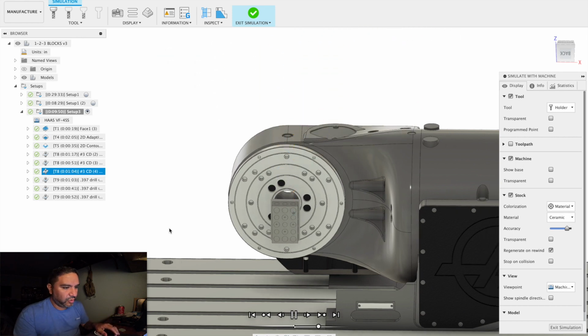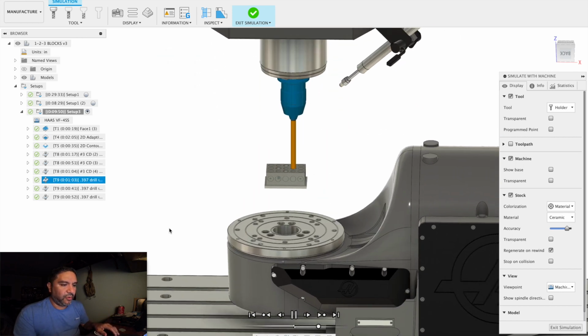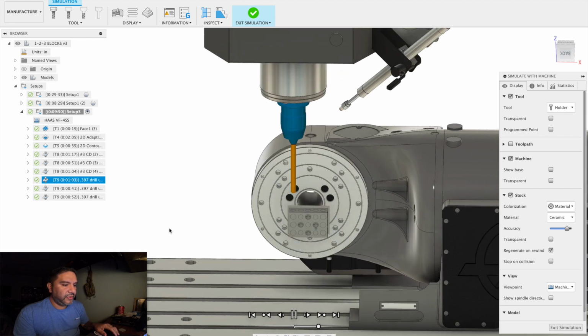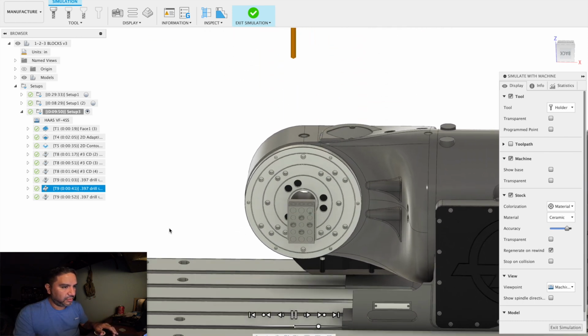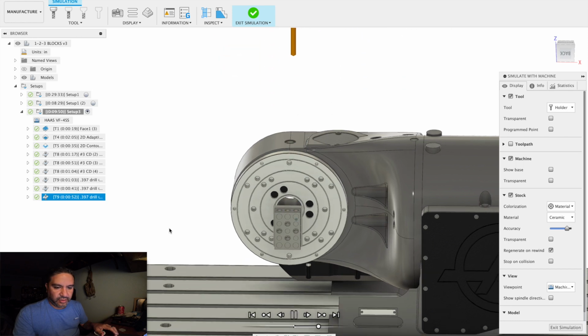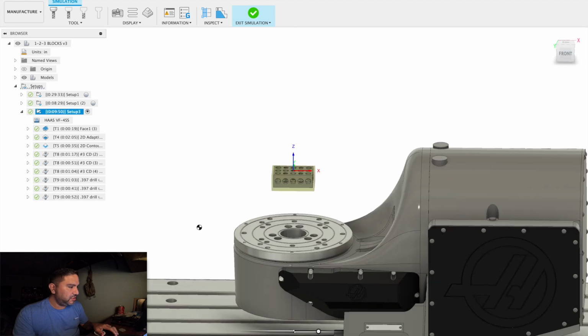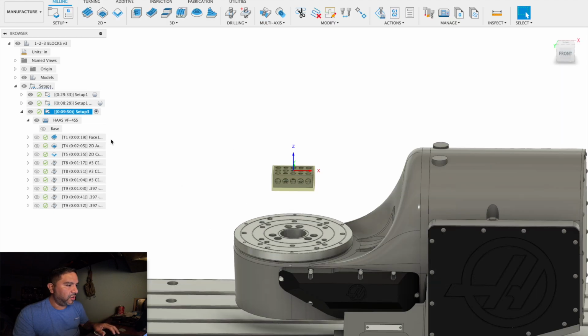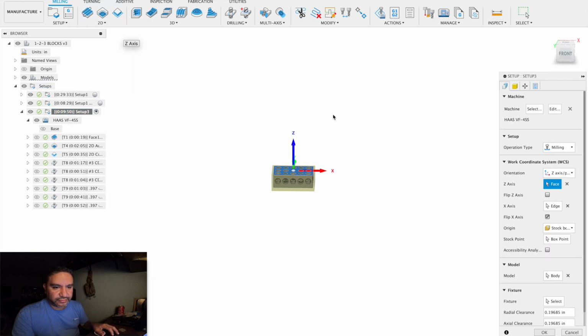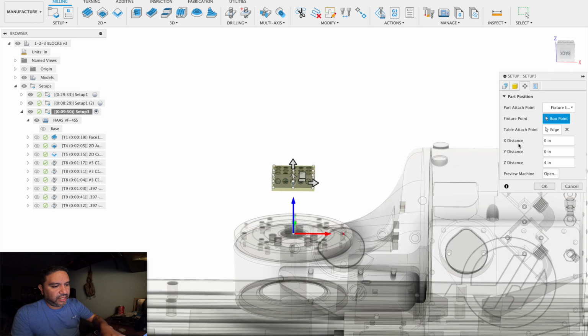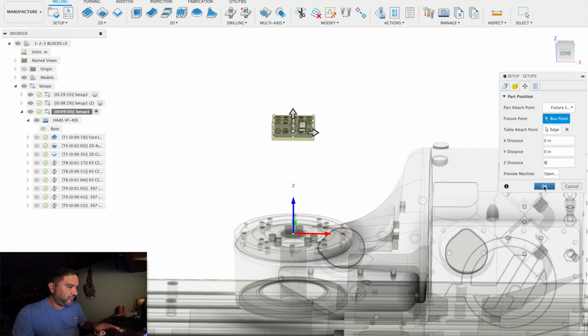Now I'm going to show you one more thing to show you why the swing number is very important. Let's exit the simulation. We have a gap here of 4 inches. Our chuck or whatever work holding situation we have going goes there. Let's say it was taller. Let's say it was 8 inches. Much higher. Reduces our Z machining envelope, but still, let's say that's all we have.